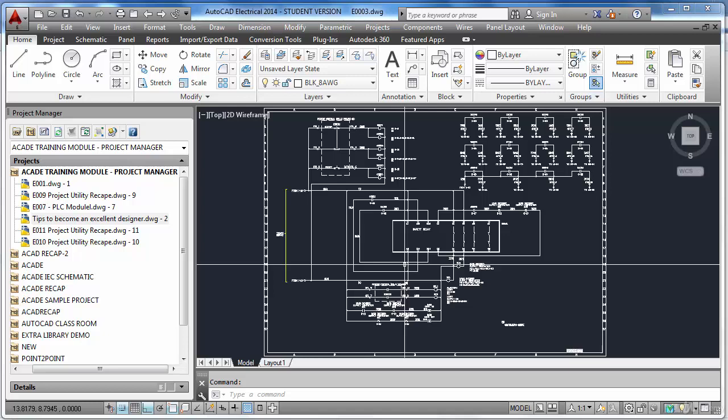Normally what I do is, if we can accommodate one set of drawings in 2 or 3 sheets, I will provide 5 sheets, because in future we may require to add few more drawings. So I will provide 5 sheets for particular section, next 5 for particular section. In that way we should plan initially before start doing anything.